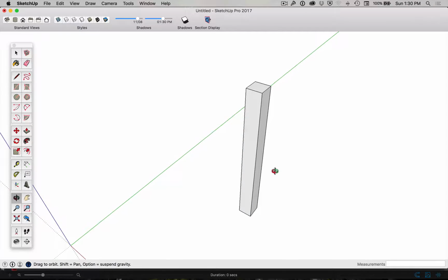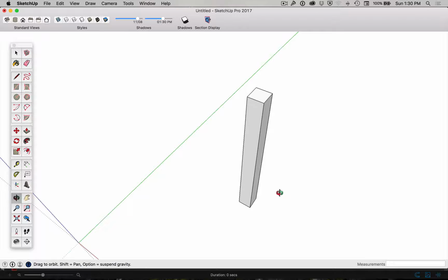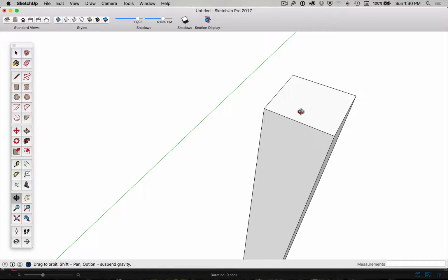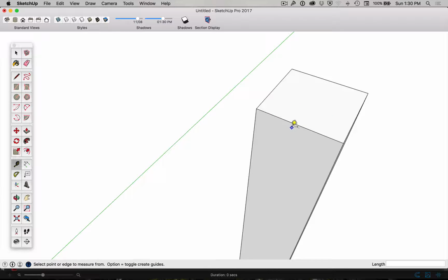We might attack it by putting a chamfer on it first. Now there's a chamfer on the outside edge, so let me pretend that's the outside edge there. If I'm going to do a chamfer and I want to do it 2 millimeters in, first of all I'll just hit my T for tape measure tool. And guys, I am not going to show you all this clicking around. I'll talk you through the tools that I go to, but as you can see here, if I hover over the tape, it says T for tape measure. That's the shortcut. So this is intended to be a quick video.